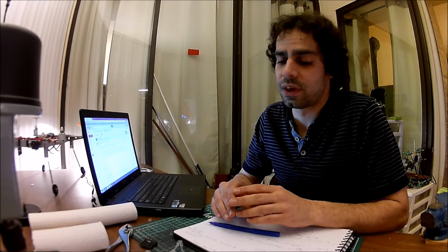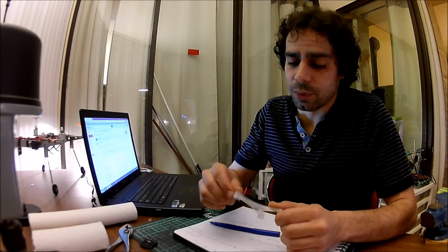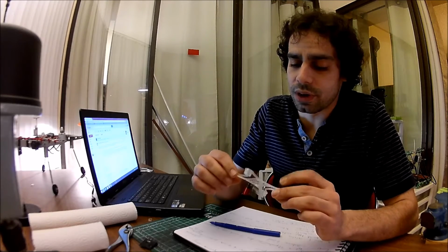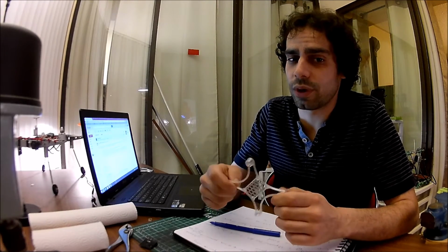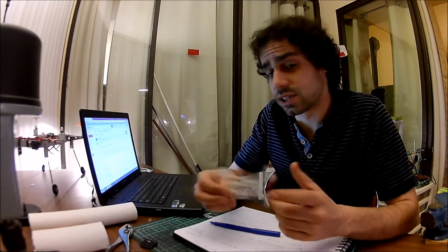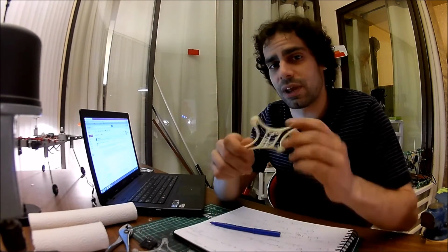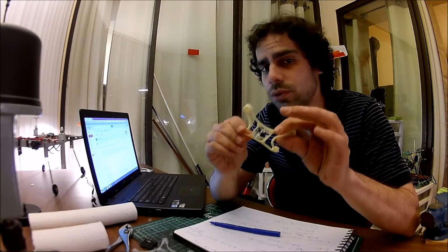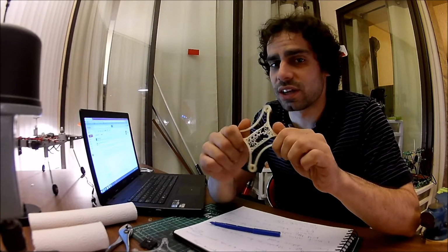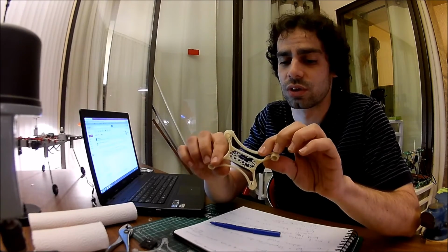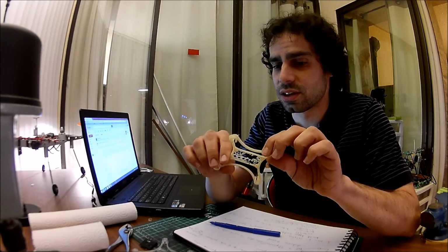So if you want to make parts out of a general thermoplastic such as ABS plastic or PLA, these are really common plastics. ABS is what Lego is made out of. PLA is the most common plastic for 3D printing right now, and they're both pretty good plastics. PLA is an organic plastic, so it's made out of plants. It's biodegradable, but as a consequence, it also has a pretty low melting point. At 40 degrees, 50 degrees Celsius, it becomes quite soft and is pretty much useless for holding structure. ABS plastic is more flexible, but it's also a lot more durable and can withstand higher temperatures. So it's an excellent thermoplastic if you're looking for a more professional material or a more usable product for your 3D printed parts.